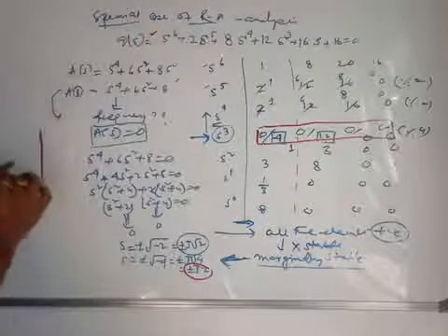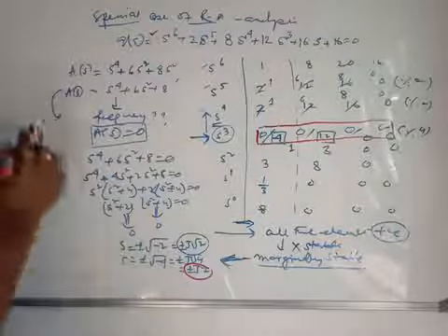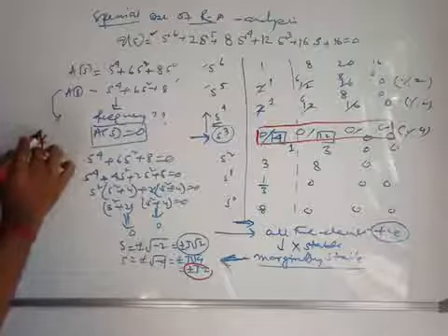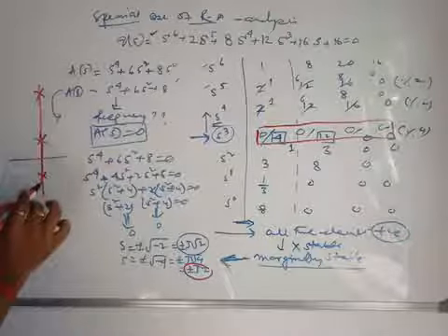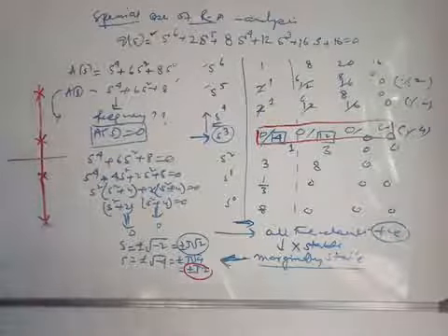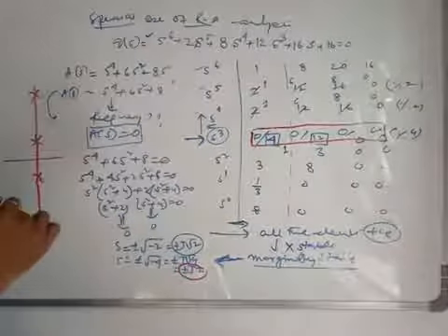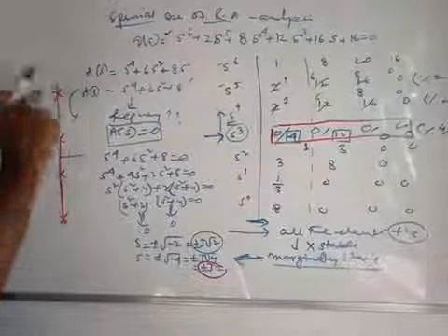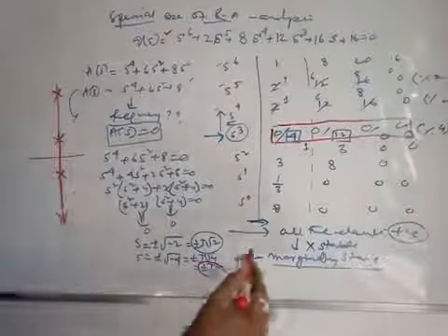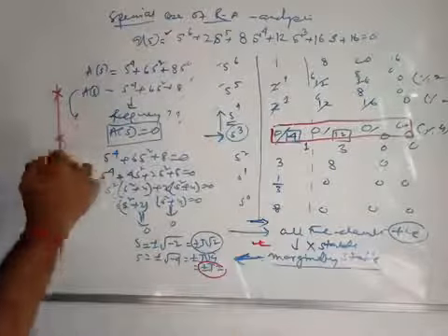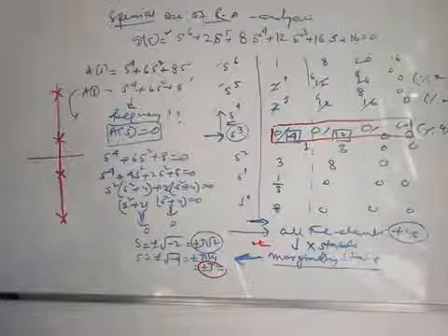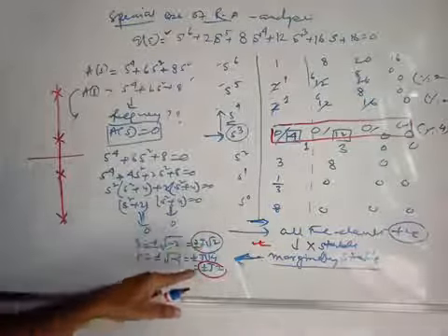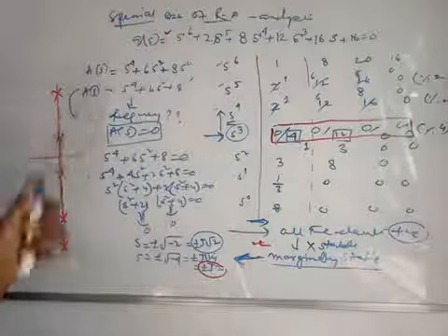So in the S plane there may be poles like this, and there may be poles like this. That is the pole locations. You see, the pole locations are on the imaginary axis. So definitely this is marginally stable, and this proves it. And once you see the locations are plus minus j root 2 and plus minus j 2, how to find the frequency?